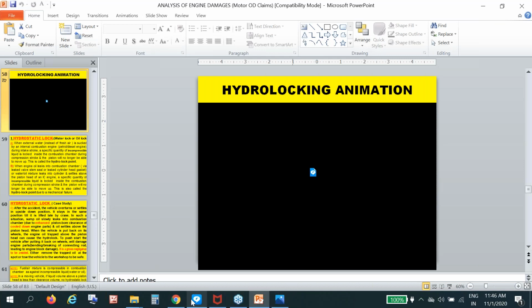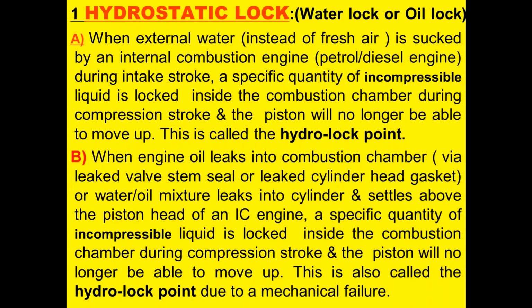Now let us move to the next slide, hydrostatic lock. You have seen how the hydrostatic lock happens. The water lock or oil lock. When external water instead of fresh air is sucked by an internal combustion engine, petrol or diesel, during the intake stroke, a specific quantity of incompressible liquid is locked inside the combustion chamber during the compression stroke, and the piston will no longer be able to move up. This is called the HYDROLOCK point.